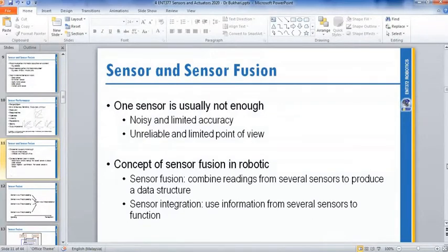That means the working path, we call it the corridor, is clear. No people in front of the robot. So both sensors pass, and then the robot will check the last sensor, the tactile sensor or touch sensor. If nobody touches the body of the robot, then the robot moves forward or backward or turns, or does anything it wants to do. So it does not depend on one sensor. That one we call sensor fusion.